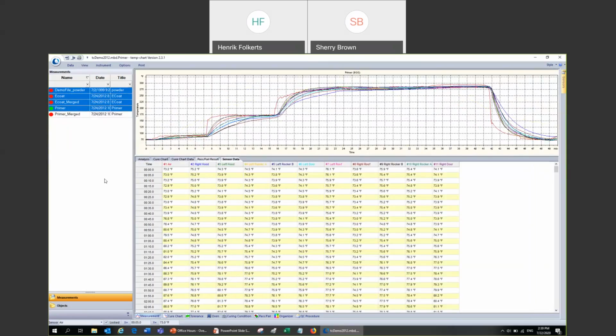We would take all the different readings and put them over time and make sure that you're running the same type of curve for all the different things. But that's also sort of what the tolerance is for. Once you establish an optimal temperature curve, that's when you apply those tolerances, that gray area that you want to be within, so you can see visually whether your temperature curves are inside or outside of that optimal area. Chad, I'll unmute you. Did that answer your question, sir?